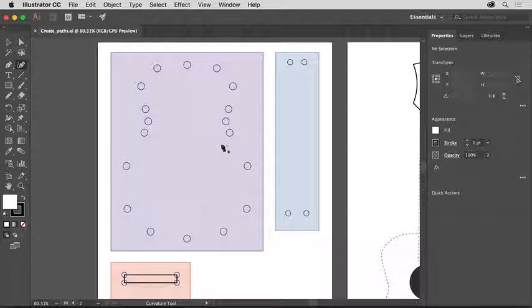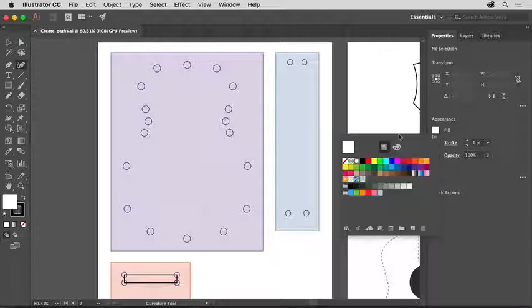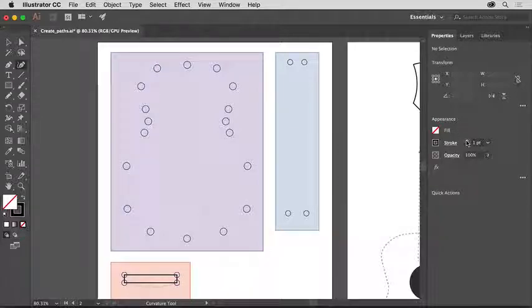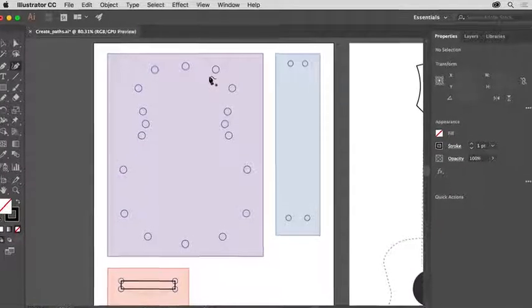Before you start drawing, in the Properties panel to the right of the document, click the Fill Color, make sure the Swatches option is selected, and choose None to remove the fill. Make sure the stroke weight is also set to 1. The fill and stroke you set now will be the fill and stroke for the artwork you draw. The circles in the document indicate where you'll click to set anchor points for a path.